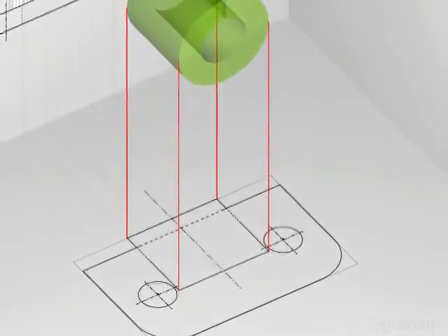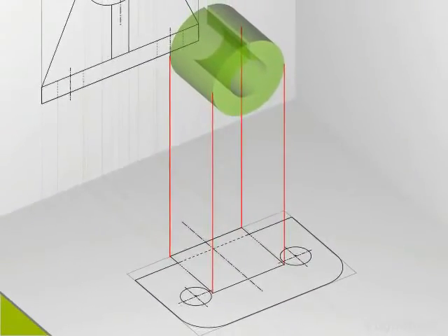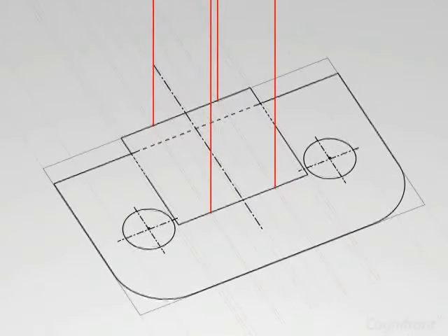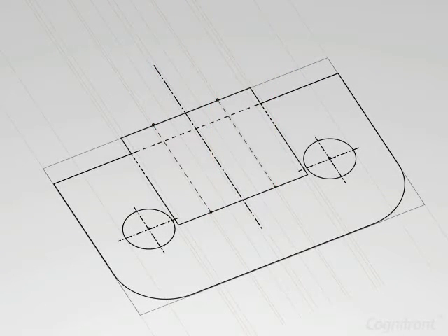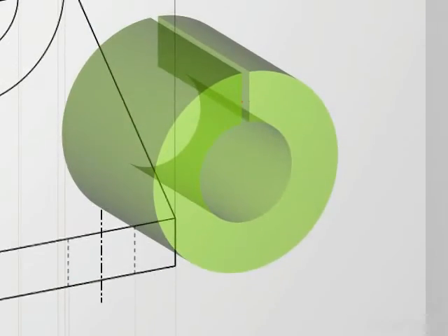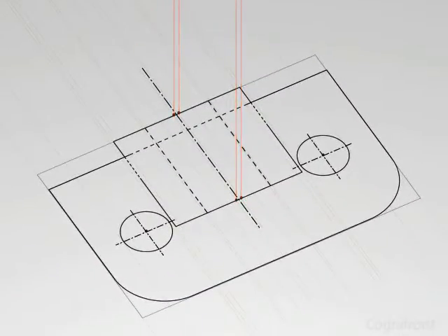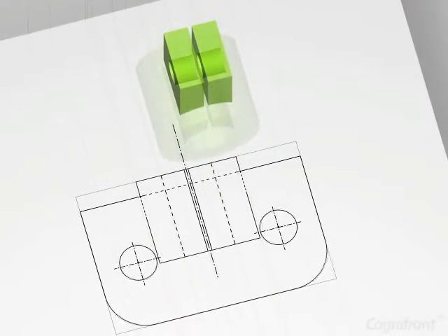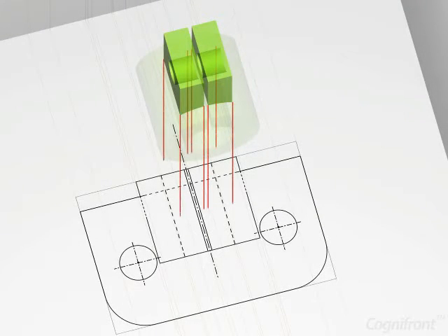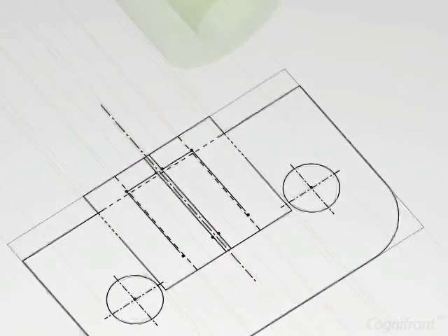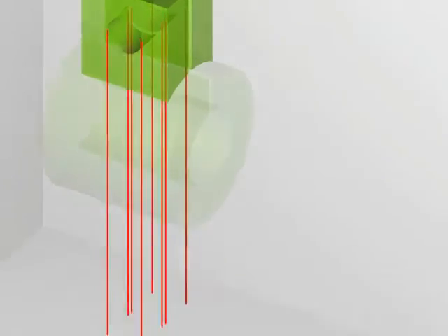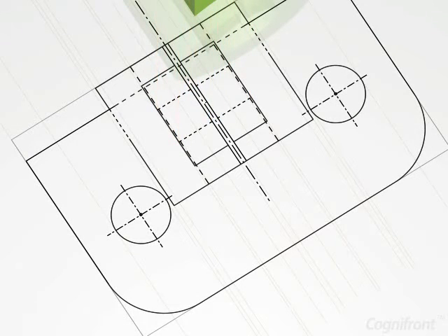The dotted center line indicates that this is a cylinder. The cylinder has a hole. So the dotted lines are drawn for this hole in the top view. Now let us generate the socket for the cylinder. Let us now draw the block with the socket. This block is on top of the cylinder. Observe that the hole going through the socket is shown using dotted lines and a center line. The center line has a dotted pattern.